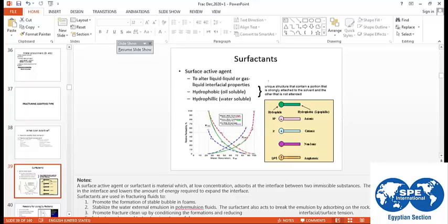Thank you so much. Another question: why do we always use 2 proppant sizes during the frac operation, like 16/30? However, using one size only gives higher permeability and conductivity. No, 16/30 does not mean that we are using 2 sizes of proppant. We are using a proppant size range between 60 and 30, because it is impossible in actual conditions to have a single size proppant. So we define a range.